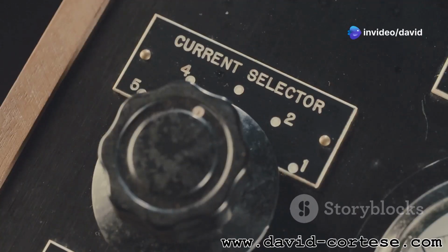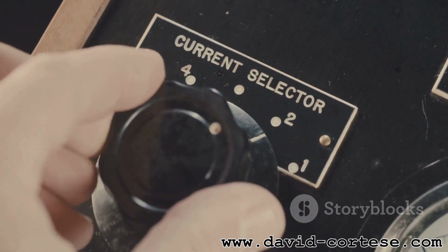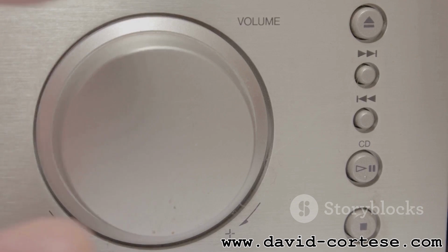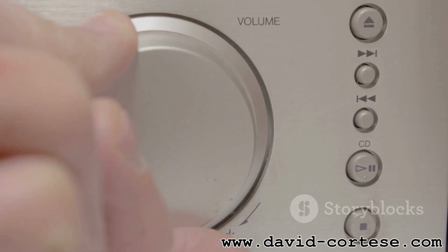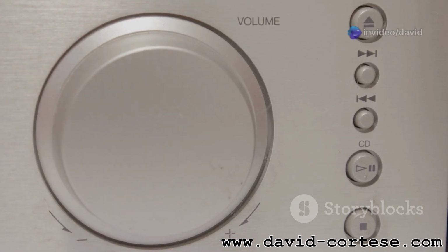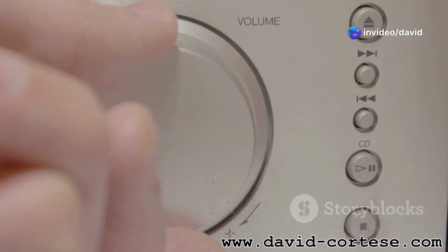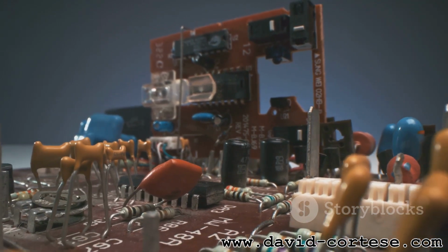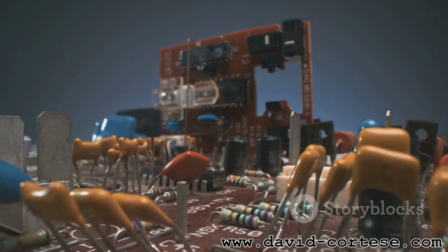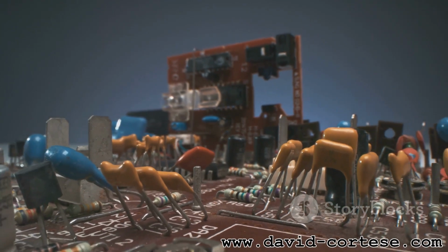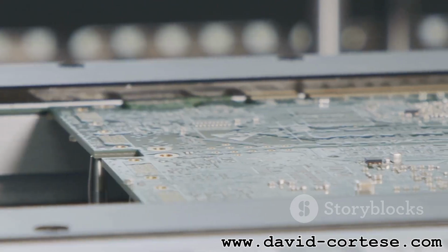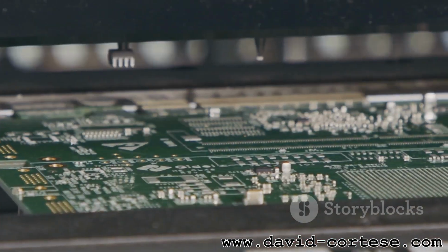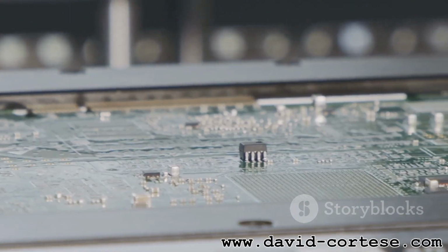Variable resistors. Unlike fixed resistors, variable resistors allow us to adjust the resistance value. These resistors, also known as potentiometers, are commonly used in volume controls, dimmer switches, and other applications where we need to vary the amount of current flowing through a circuit. Each type of resistor has its own set of advantages and disadvantages, making it essential to choose the right type for the specific application. Factors to consider include the required resistance value, tolerance, power rating, and environmental conditions.